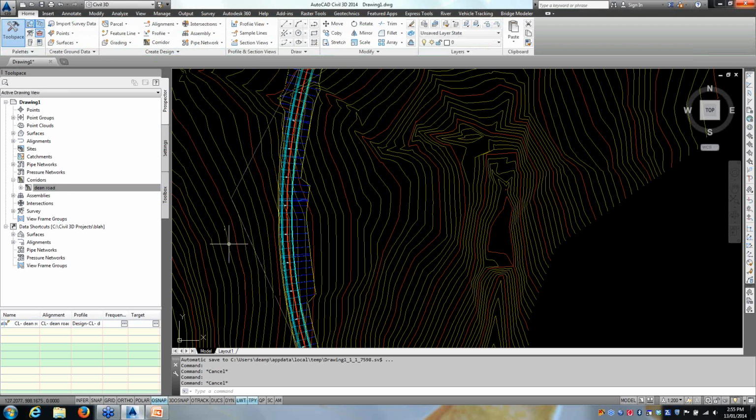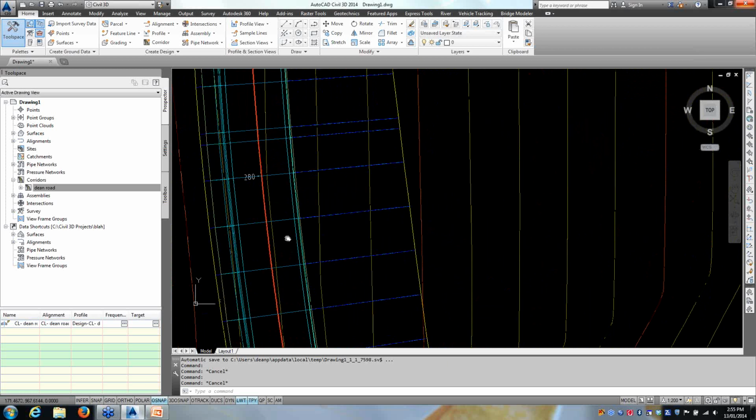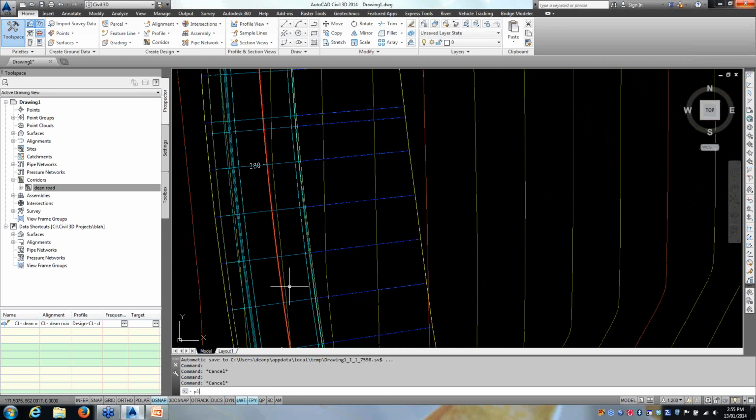We're going to, first of all, draw, in this case, it could be a 3D polyline, 2D polyline for the alignments, 3D if you want to do the elevation as well. I'm going to use, in this case, an actual alignment and a profile to play around with, just give me a little bit more control than a 3D polyline, but you could use either. So I'm going to actually start with a 2D polyline.